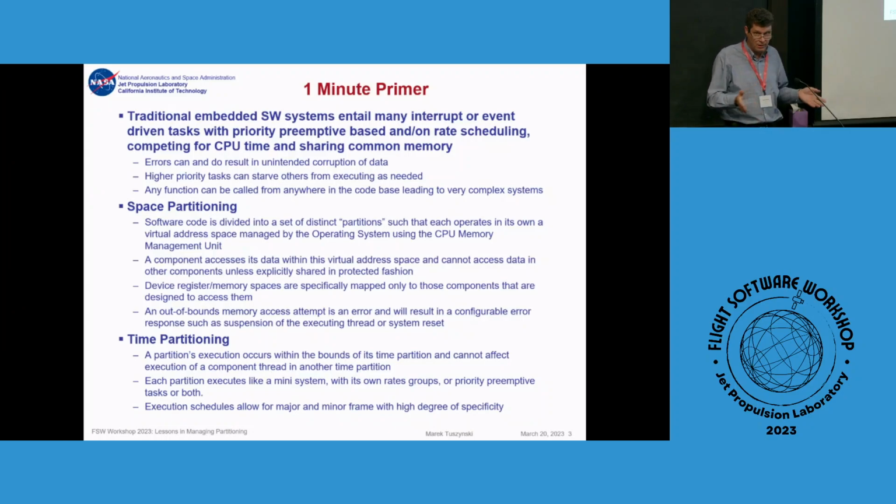And there is quite a bit of variability that you can employ. You don't have to just time slice it into a set of bins and everybody runs at the same rate. You can have time slices shared, so you can control that in one sort of minor frame. This one runs in that time slice, and another minor frame, another partition runs. So there's lots of variability, and depending on the RTOS, there's a little bit more flexibility on what you do with background tasks too.